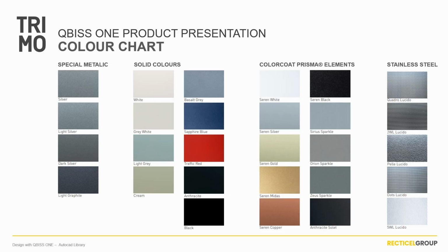We offer a big range of different colors, but we most commonly refer to the qbiss.support color chart and RAL card. For other colors, please check with Trimo technical department. We can choose from advanced coatings, PVDF or PUR-PA, for durability and aesthetics. The most harmful part of the element is the face side. It is exposed to environmental impact, therefore it must be well protected in order to last long. I would say that we discuss corrosion with confidence.